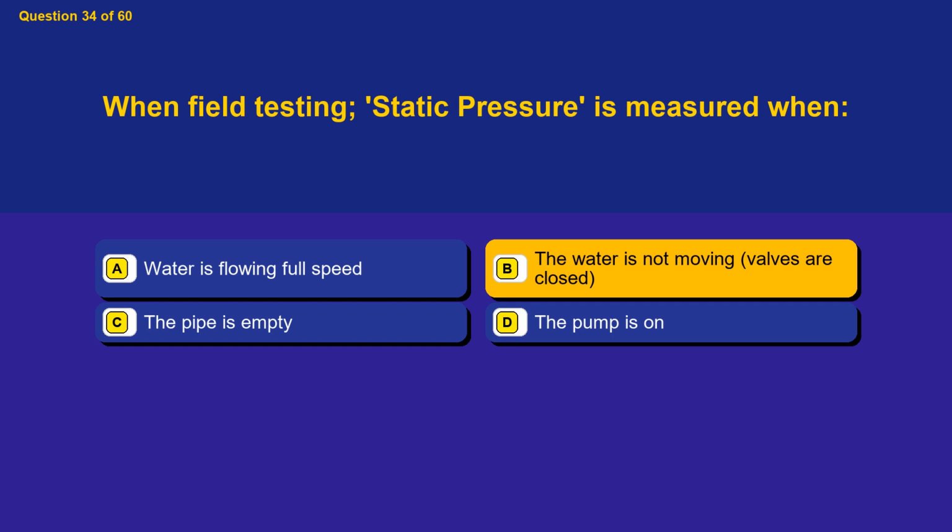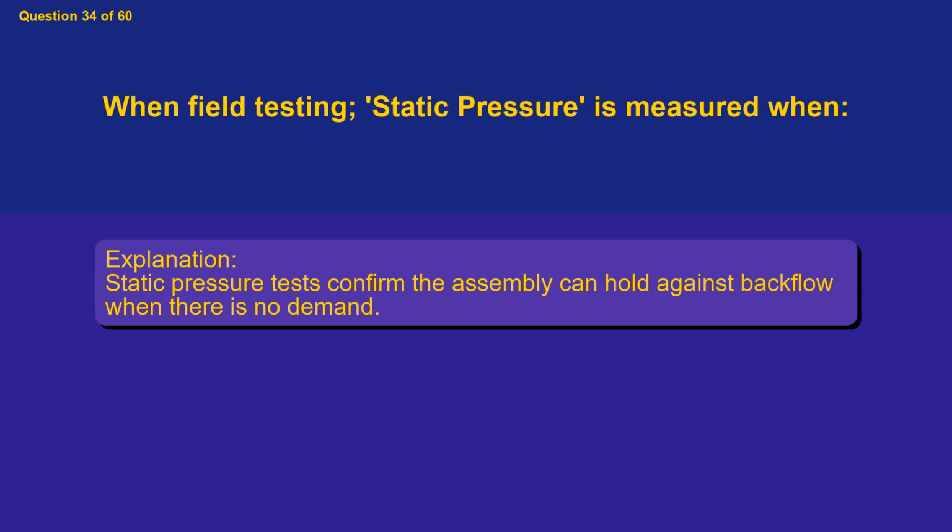The correct answer is option B, the water is not moving, valves are closed. Static pressure tests confirm the assembly can hold against backflow when there is no demand.